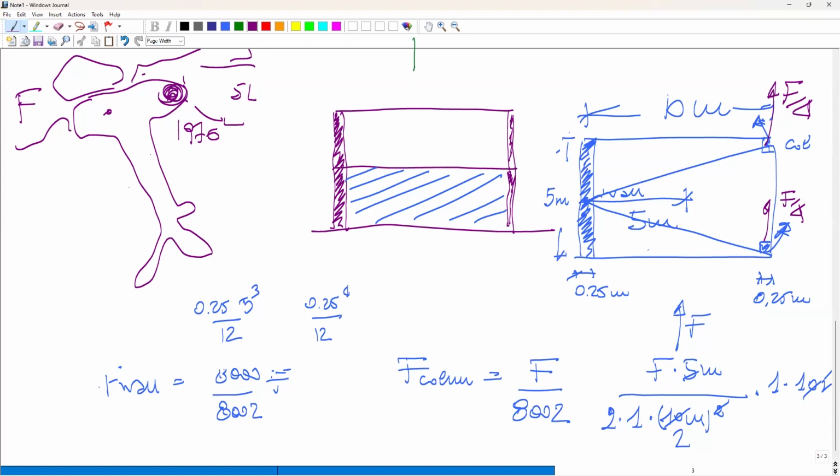And because of equilibrium, the force in the wall you cannot calculate with the same formula because we are going to the limit where the center of stiffness is 0. But this actually is unloaded of the same quantity. So those 2 columns, it's not true that they were not taking almost anything. They were actually taking each one 1/4 of the force.